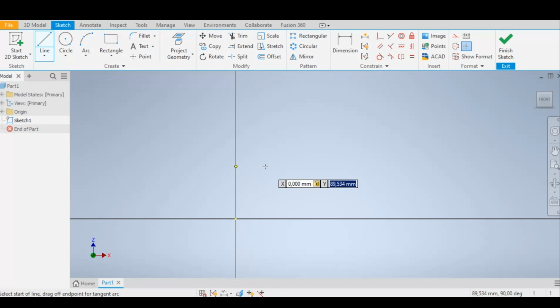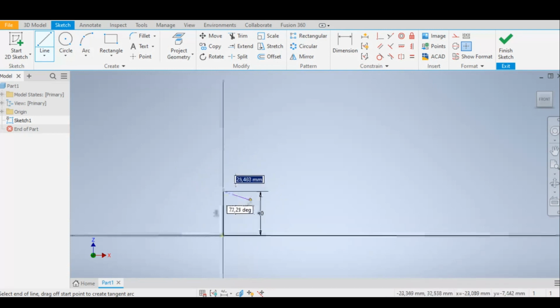So let's say we want to start the sketch at the origin, so let's do an X and a Y of 0, and once I click tab again, you will see a preview of this point on your drawing environment. So once you're happy with this, I can simply click enter to continue my line from here. So we can see our line is now situated at the origin, and from this we can do a line with a length, and you can even set your degrees for that line if you would like. So to simplify this, I'm simply going to draw just a simple part just to show you guys exactly how this would look.